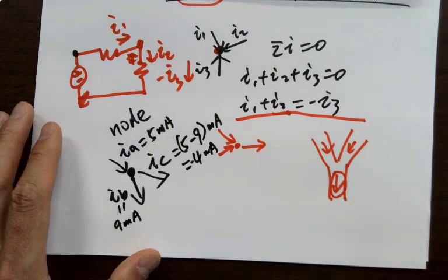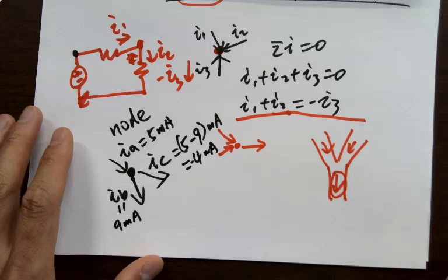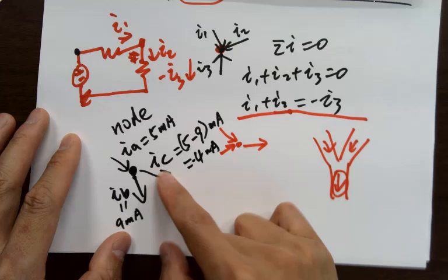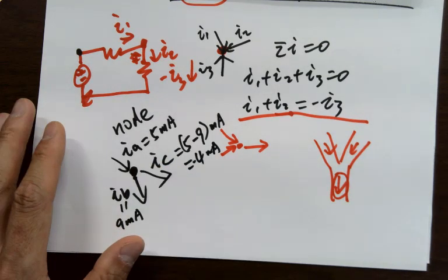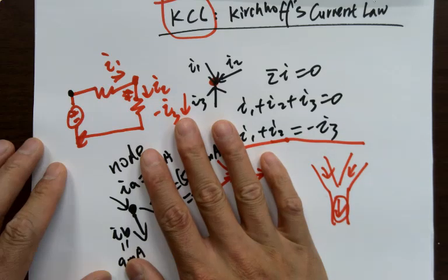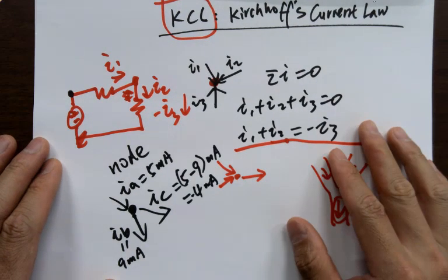Okay? So the actual current is actually flowing into the node, because it's getting a negative current flowing out, so it's actually flowing in physically. However, you can always use vectors for the calculation and use KCL to calculate it without any problems. But eventually you get an answer, and it's going to carry a sign in front of it, so you'll know the real current direction in the real circuit. Any question about KCL? It is just that simple.